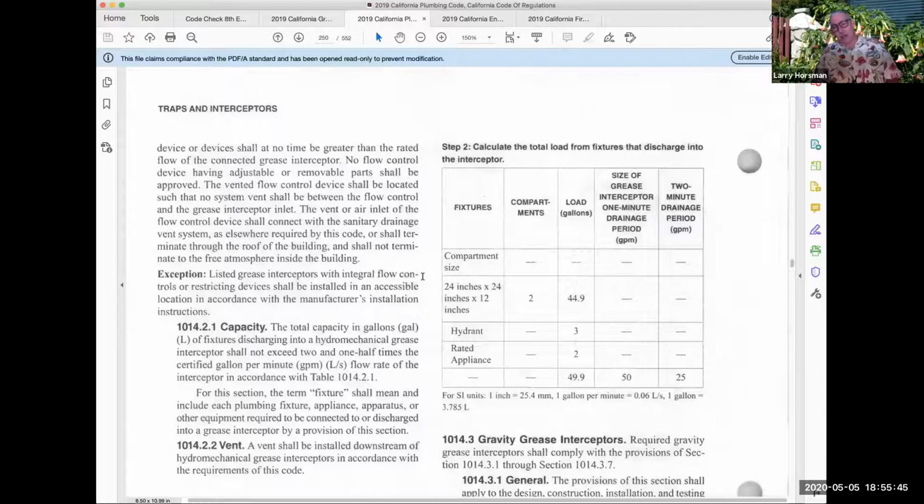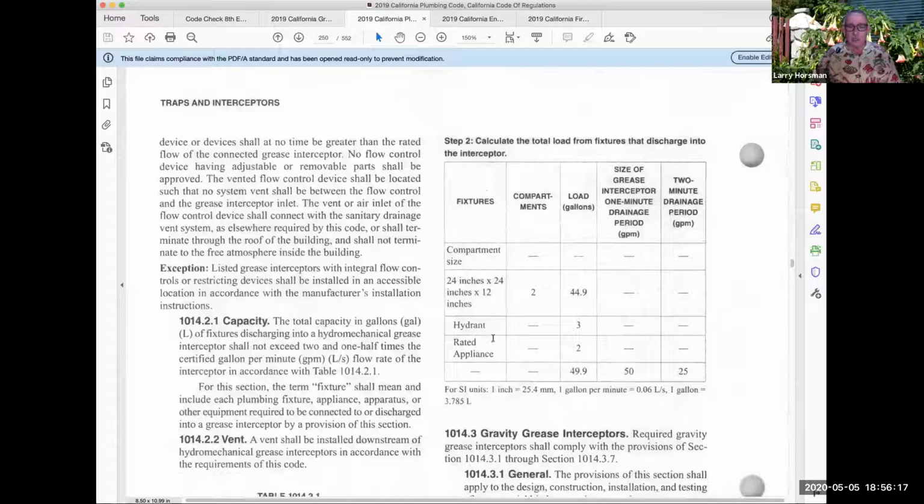They would rather not have to dig a big hole or take up a lot of space inside the building, because for an individual fixture, you may have a grease interceptor, a grease trap inside the building, but you have to maintain those. And so many of them, in order to get a permit, want a copy of your maintenance agreement with whoever comes and hauls off the grease. So those are just little things.